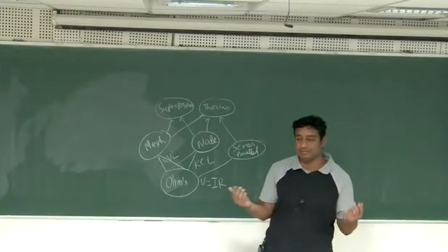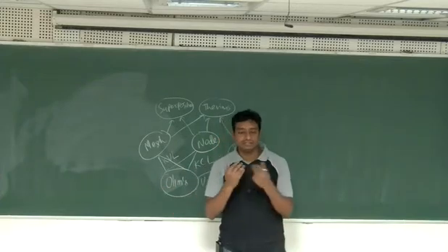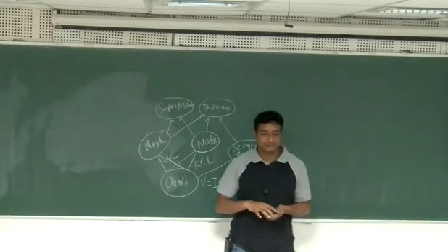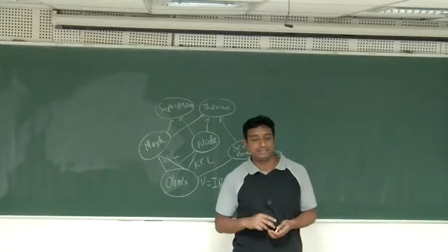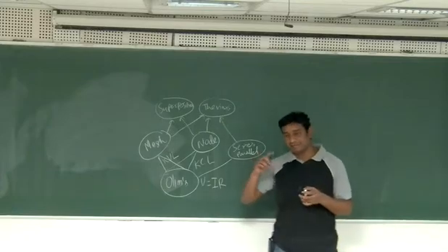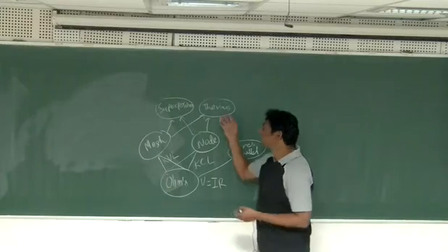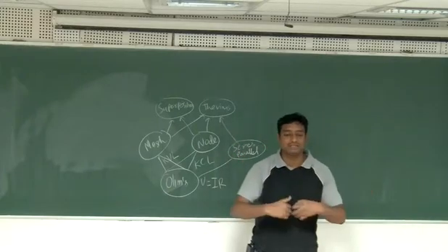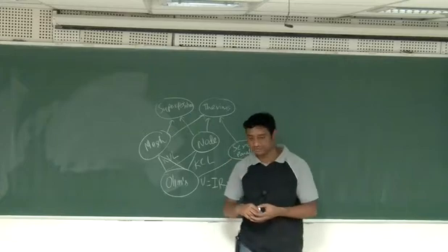It may be any complicated, complex connections. Finally, you replace it with what? With one voltage source and one resistance. That voltage source is VTH and the resistance is RTH, and then you connect back your load resistance and find the load quantities. So what Thevenin's theorem is saying is that a given circuit can be replaced with one voltage source and one resistance.